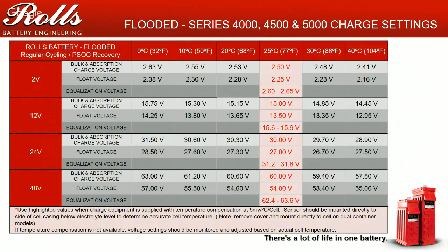Again, what you want to do is look at your specific gravities on a quarterly basis, and make charging voltage adjustments. So based on how much load the customer's running, based on how much you're charging, and based on the seasons. And most systems, in April and September, you're going to adjust charging voltage settings. Customers who leave systems at one set point all the time very rarely are going to have decent specific gravities year round. You might have great specific gravities in summertime, but they might fall off a little bit because your wintertime production is a little different than your summertime production.